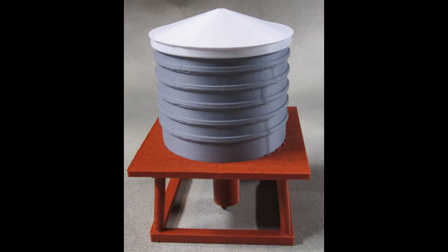When printing the rooftop tank, I print the platform, cone, and tank separately and glue them together. I usually print the tank and cone without supports and suppress the tongue on the cone to achieve a perfectly flat bottom surface. I then center the cone manually on top of the tank and glue.